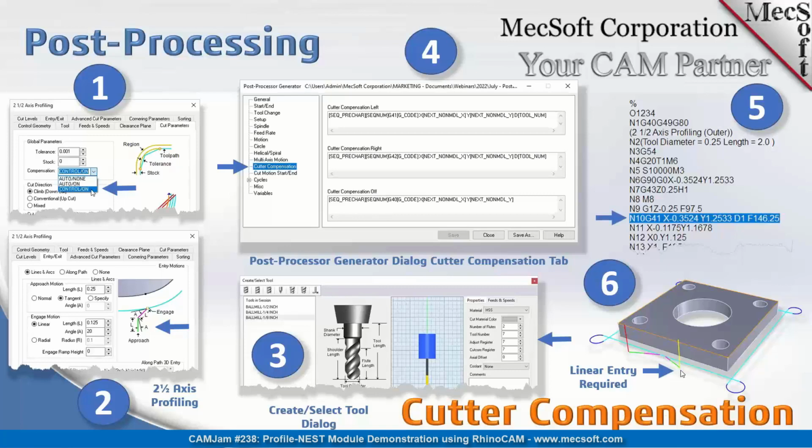Then you're starting your approach motion in green, and then your magenta motion is your engage. So this needs to be linear. The first approach motion needs to be linear for sure. So if you just set them all to linear, then you won't have a problem.